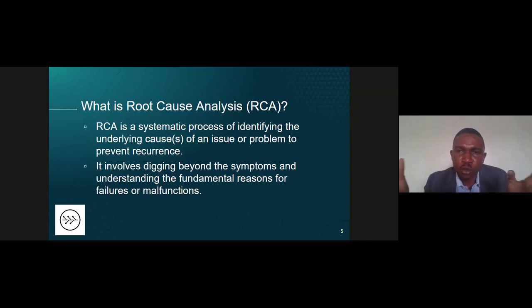So let me give a typical example of what all of this is about in this root cause analysis. Now, in a chemical plant, you have heat exchangers, boilers. You see that they are failing. When it fails, what are you going to do? I just quickly want to fix the problem. Maybe there's a leakage in one of the exchangers, so you just plug it and you continue running the process. That is just a temporary solution to the problem.